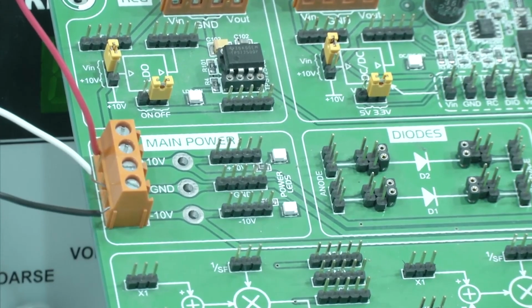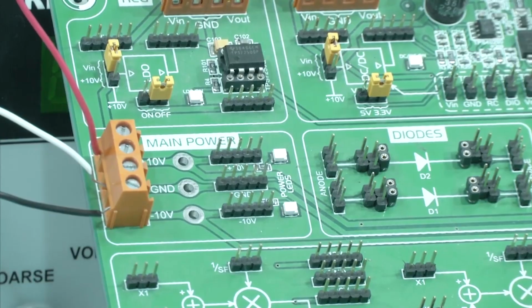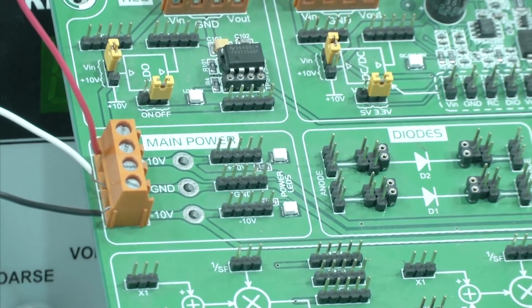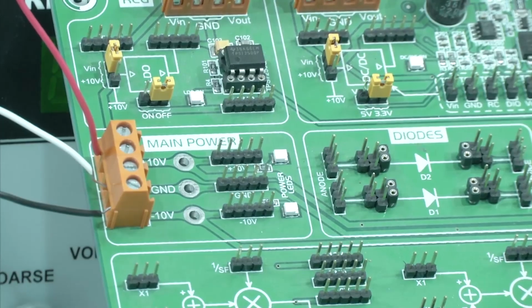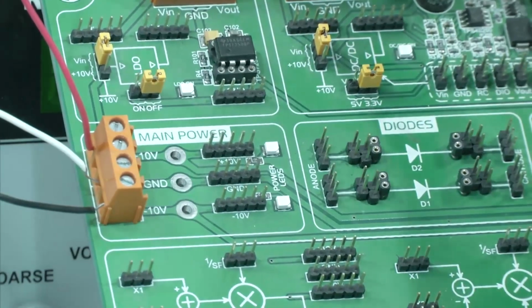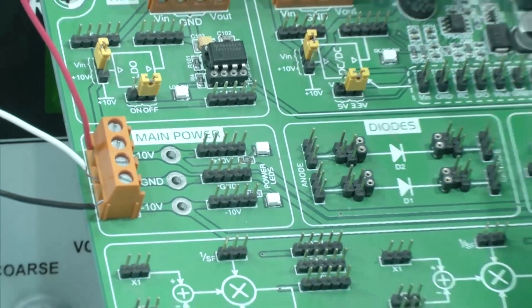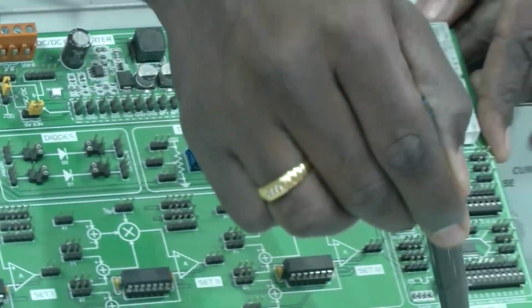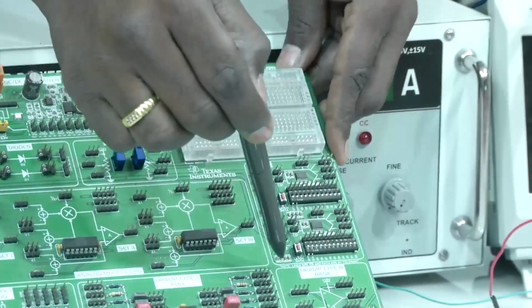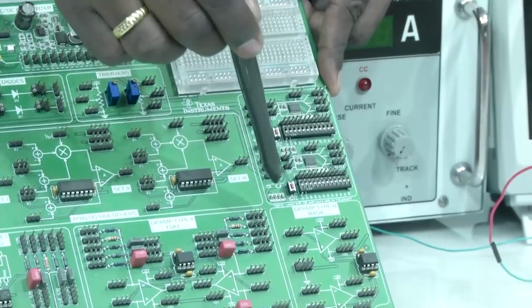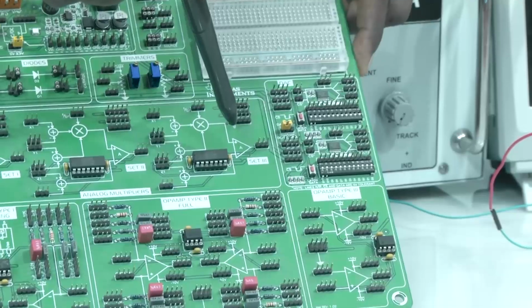The op amp can be powered by even slightly more than plus or minus 15 volts, but we are using plus 15 and minus 15 because in our simulation and in our theoretical calculations of higher threshold and lower threshold, we have used plus 15 and minus 15. Now, what we do is use this particular portion of the op amp, and this portion does not contain any resistors, but we require resistance, isn't it.